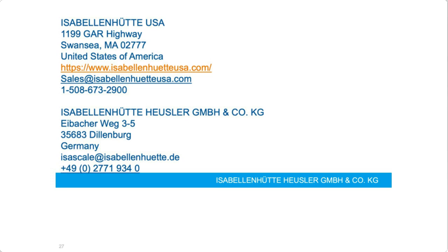Yeah, this is a question that depends a little bit on the product that we look at. But for the IVT third generation, this product has a galvanic isolation of 1,000 volts DC, basic isolation level. So that's the working voltage that we rated it for. It's rated for peak voltages of 6 kilovolts for transient overvoltages. And the voltage sensing capability goes along with the actual voltage rating on the product, so it's also 1,000 volts.